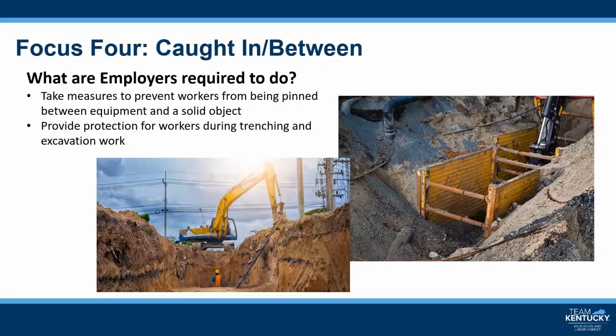This could include spoils that could fall into the trench and bury the workers. Mobile equipment used near or over an excavation presents a hazard. When mobile equipment is operated adjacent to an excavation, or when such equipment is required to approach the edge of an excavation, and the operator does not have a clear and direct view of the edge of the excavation, then a warning line must be utilized, such as barricades, hand or mechanical signals, or stop logs.